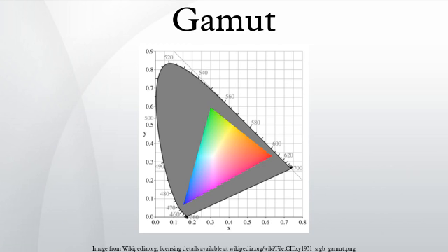Liquid crystal display screens filter the light emitted by a backlight. The gamut of an LCD screen is therefore limited to the emitted spectrum of a backlight. Typical LCD screens use cold cathode fluorescent bulbs for backlights. LCD screens with certain LED or wide gamut CCFL backlights yield a more comprehensive gamut than CRTs.